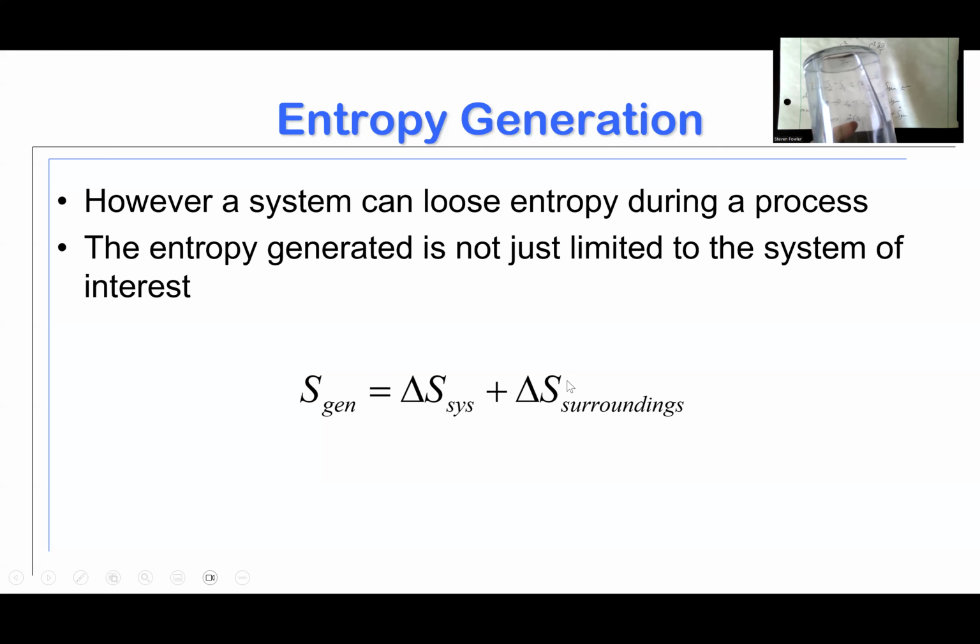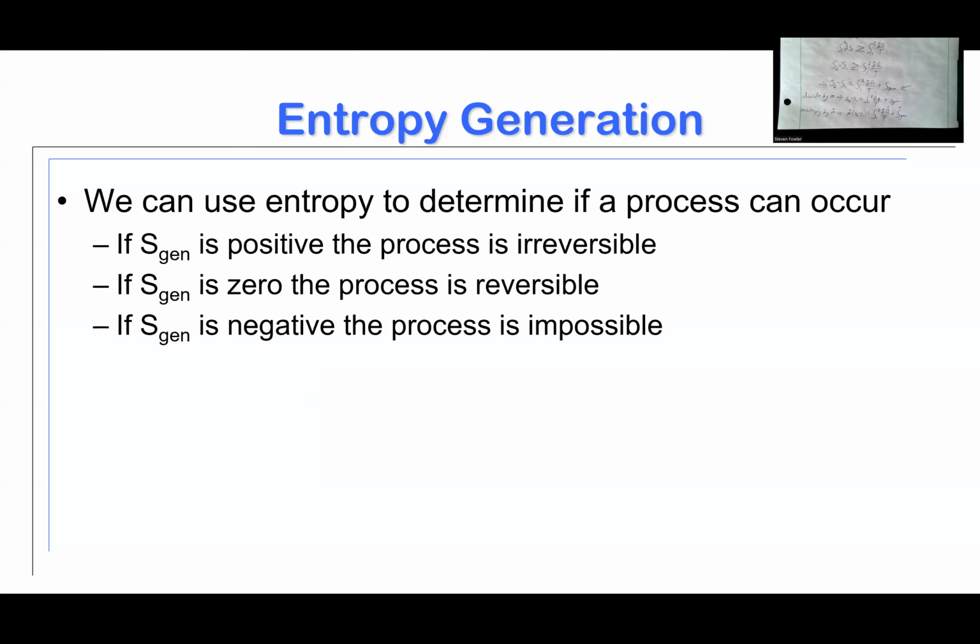Basically, a heat pump is a device that decreases the entropy of the surroundings, but it increases the entropy of the system by doing so. And what we find, again, for this inequality to be preserved, is that this entropy generated accounts for how much this is bigger than that. And so there are rules associated with S-gen, the entropy generated. The rules are essentially that the entropy generated is going to be greater than or equal to 0.